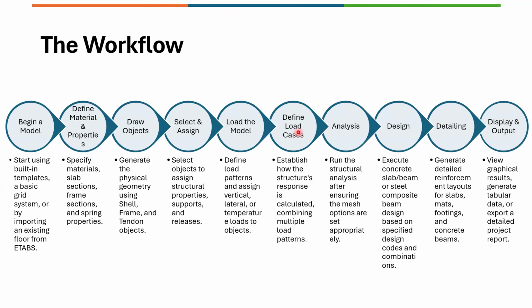So defining load cases is kind of automated for most cases, especially the linear static cases, since we are in the SAFE program. If you are importing a story from ETABS, then it could be a foundation system or a floor slab system, and can be easily imported.